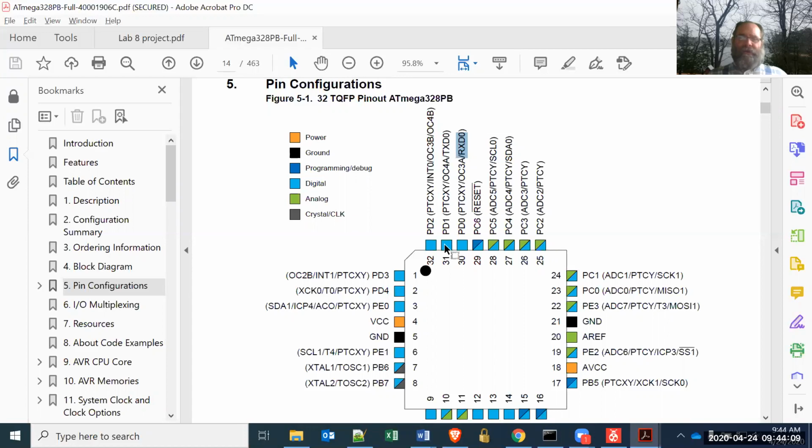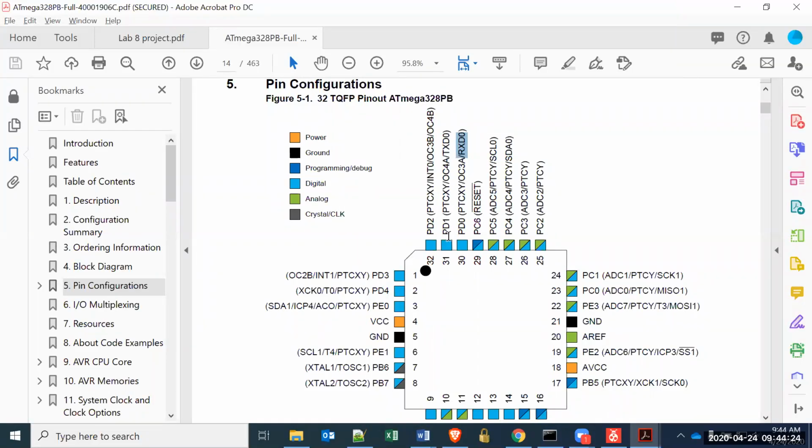Okay, you understand what's going on, AJ, don't you? Yes, I see the problem. Yeah, and I do too, and I'm not sure what to do. What's going on? Can you fill me in? Well, the 7-segment display uses bits 0 and 1, which are also the transmit and the receive. Oh, which is why it works when the shield is off. Yeah. Okay, so we have a problem. Houston, we have a problem.